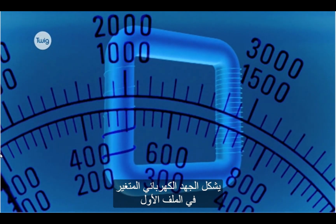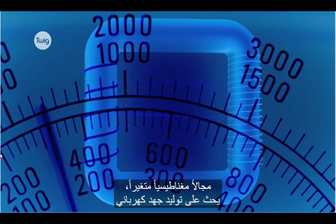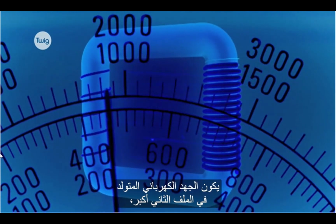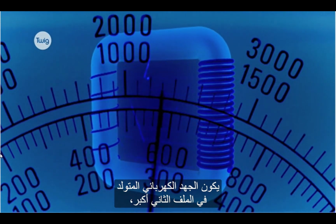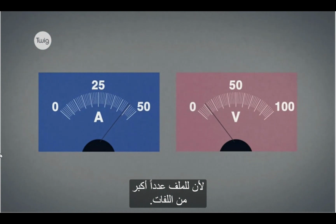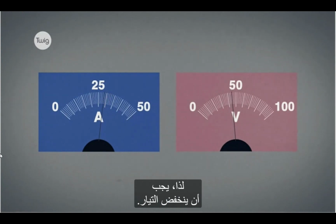The changing voltage in the first coil creates a changing magnetic field, which induces a voltage in the second coil. The voltage induced in the second coil is greater, as the coil has more turns. Because the power must remain constant and the voltage is increased, the current must decrease.